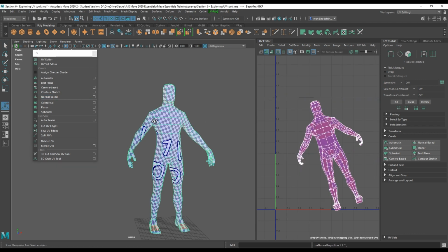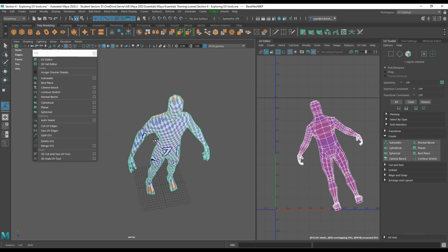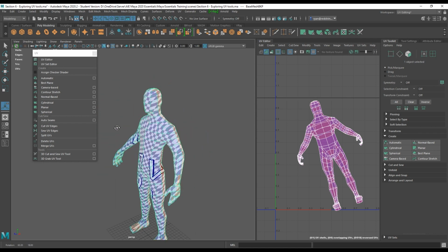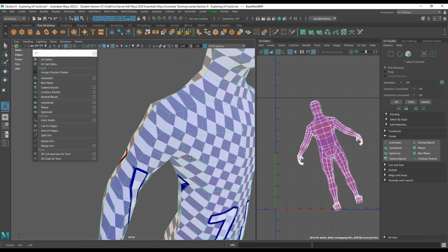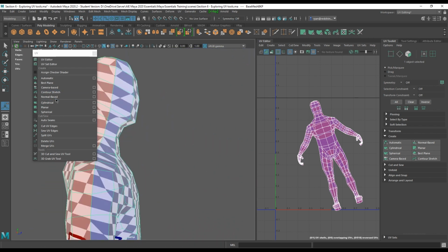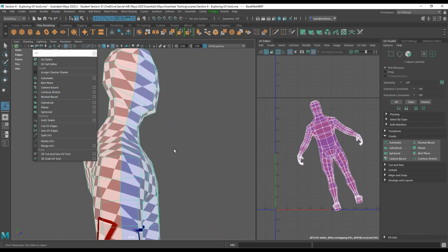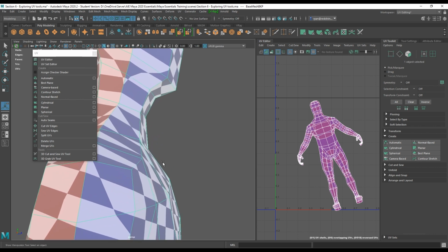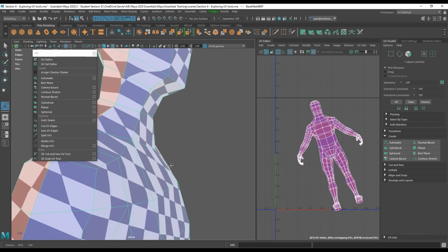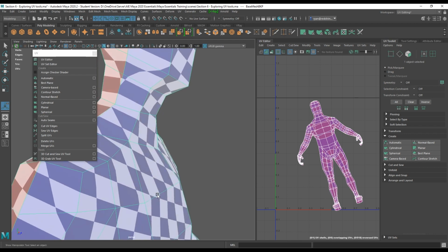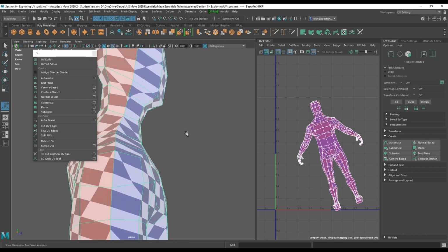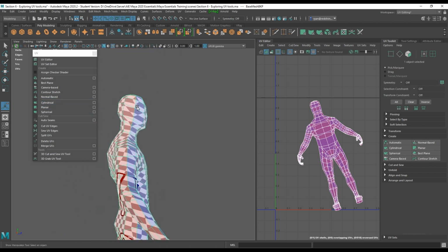So now it's looking at the face normals and trying to get an angle at which to get the best result. Now face normals means, for the normal based UV projection tool, imagine a little line coming out of the face that's perfectly perpendicular to one of the polygon faces. That is the angle at which this normal based projection method tries to get the best UVs.